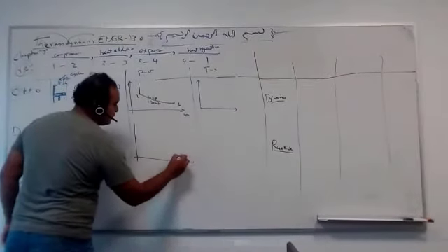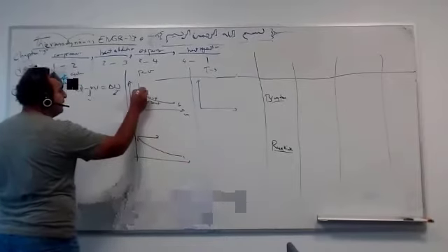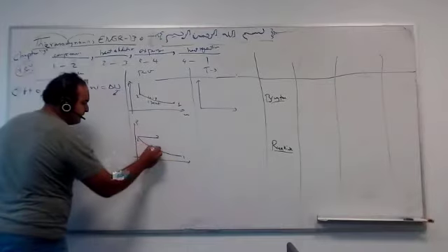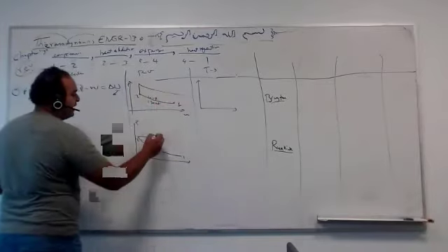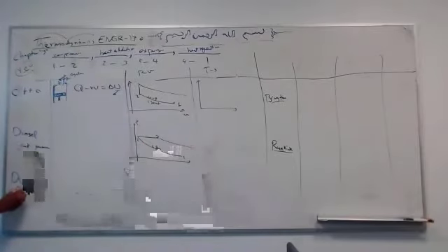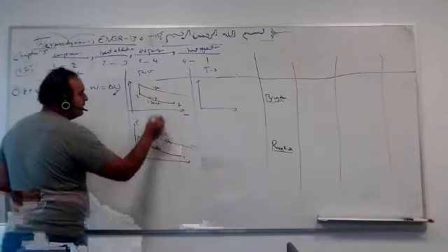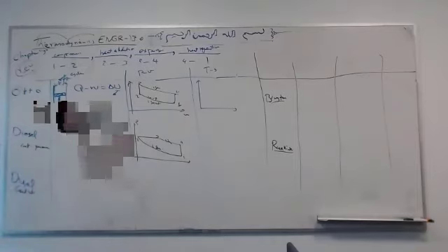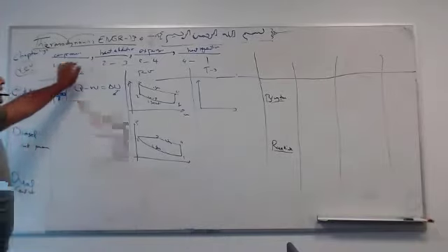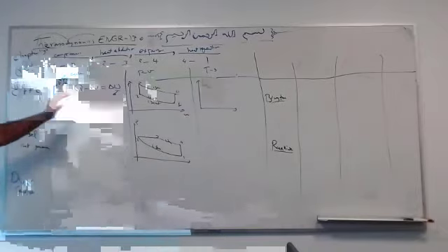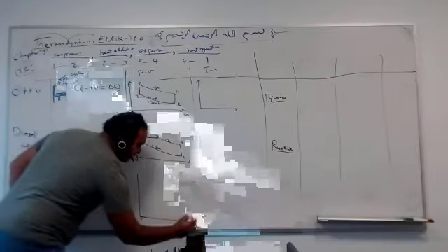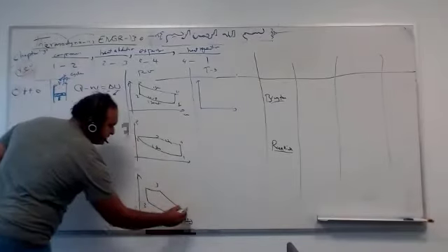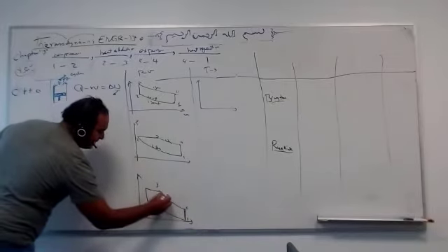So if you want to plot it, it's 1, 2, 2, 3. Here is vertical because volume is constant. Here is horizontal because pressure is constant in diesel. Exactly the same process, everything else is the same. It means expansion is what? Isentropic. Heat rejection at constant volume. So here is isentropic, isentropic. Finally, this is heat rejection. For all these cases, including Brayton and Rankine, we have isentropic compression, isentropic expansion, and heat rejection. For these three, the heat rejection is at constant volume. So 1, 2, 3, 4. The compression and the expansion are isentropic.